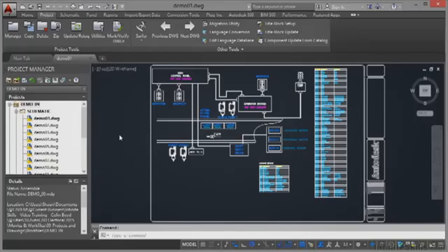And I'm not actually going to change the project at all. All I'm going to do is show you how to create a new one if you need to. Normally it's better to copy projects anyway, because then when you copy, all of the settings in the WDL, WDP and WDT files come across into the copied project rather than having to set all those up all over again.